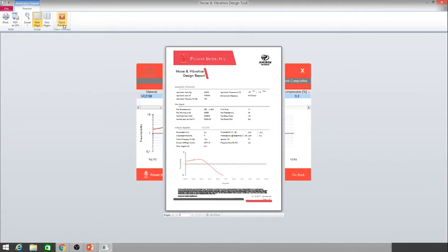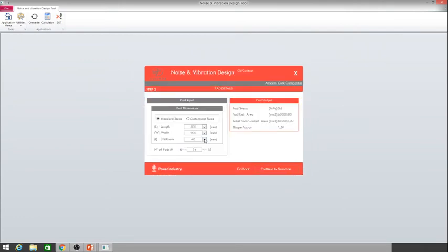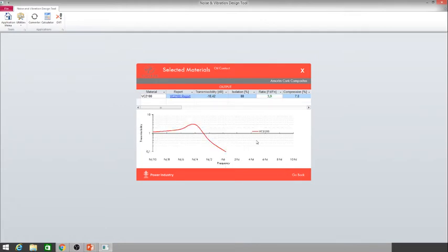We can simulate. It's an easy question. So 93 was at 40 millimeters. So if we change to 20, we're going to input again the 14 pads. So the only thing that changed was the shape factor. And if we continue, we see here the reduction in the insulation. So the insulation decreases by 5% by decreasing the thickness.